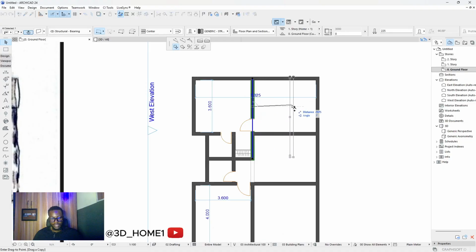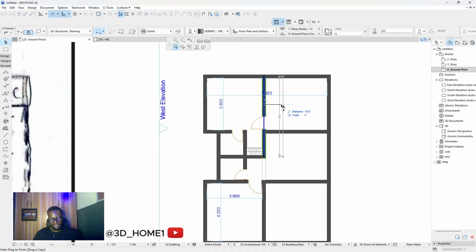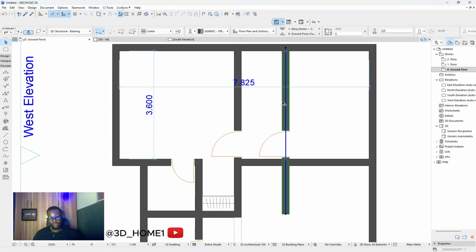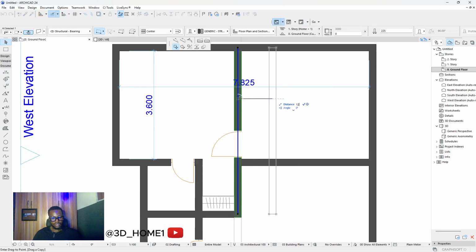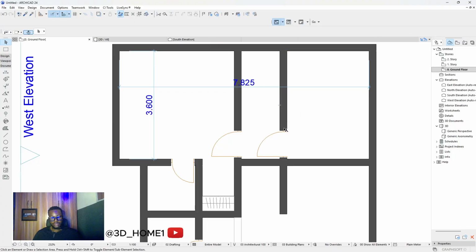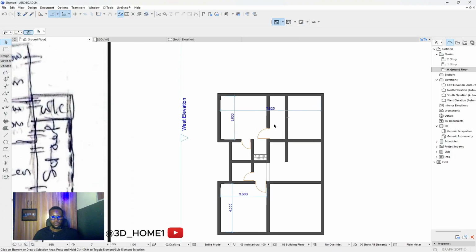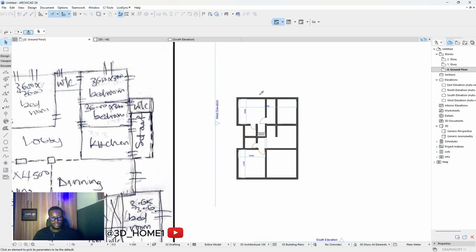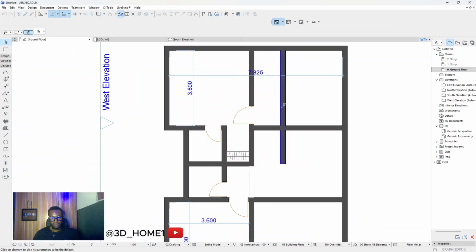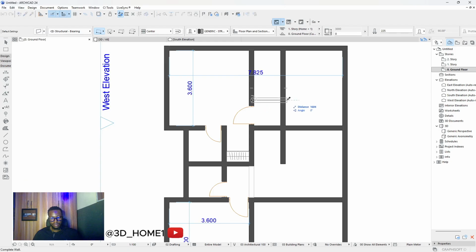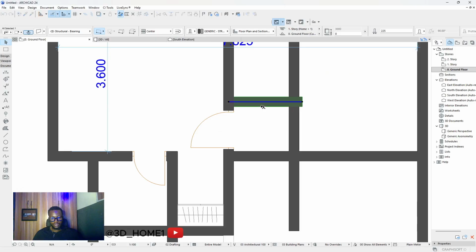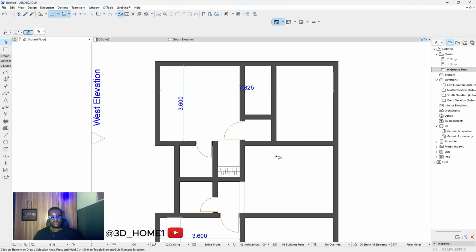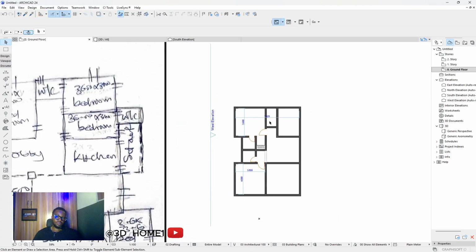Okay. Now you see that the plan is changing. So let's get this 1,500 first, or 1.2. Let's get this one 1.2, 1,200. Click here, bring it to this side. Then we remove the door, and then we need to cut this entrance. Let's do it with 900, because we don't really have much there. 900, and we are cutting this for movement.